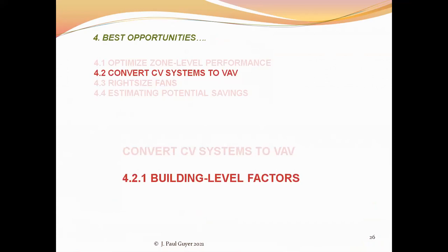So that's something to look at seriously, is to convert the system to VAV. And then of course you need to remove those legacy components from your dual duct system or your terminal reheat system from the older system. You need to obviously get rid of them.